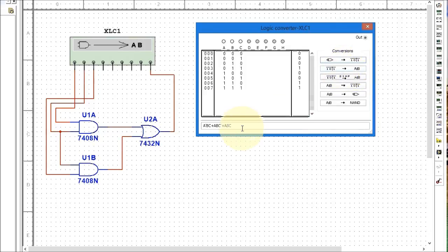So click on that, and notice it gives you A'BC followed by ABC'. So this is ABC'. Okay, so it doesn't put the bar over it, it just puts this little tick here indicating it's C'. And the next item I want to show you is it goes from truth table to simplified Boolean expression. So here we have the AB or BC.